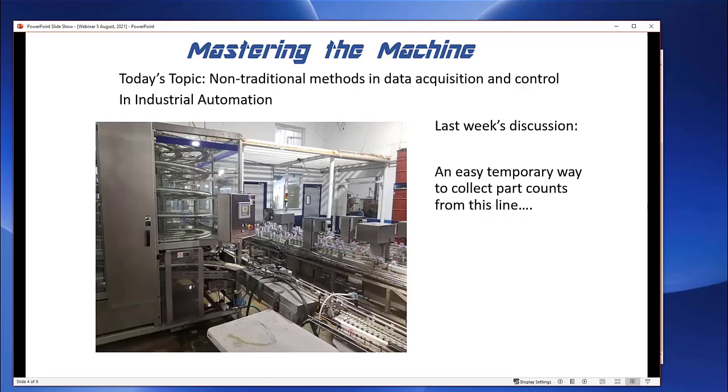He said, sure, here's the EDS file. I found a copy of it somewhere. He sent me an add-on profile. I tried to add it in that way, and it still didn't work. So then I independently hooked it up to another laptop that I have on the other side of the room, and I actually made it a much later PLC just to test it. And sure as heck, I had a version 30 PLC, and I was still not able to add it on a different laptop.